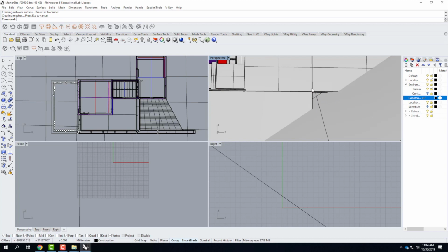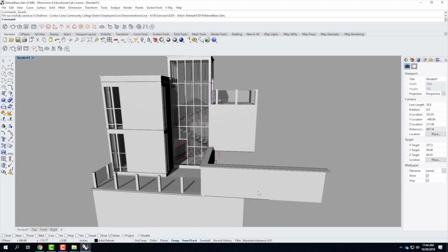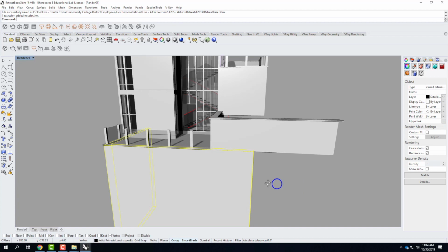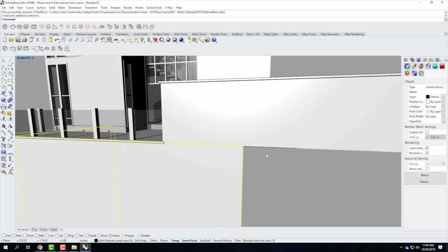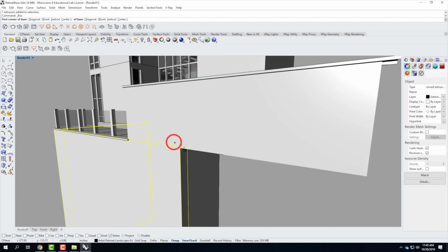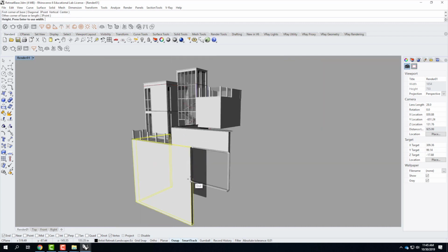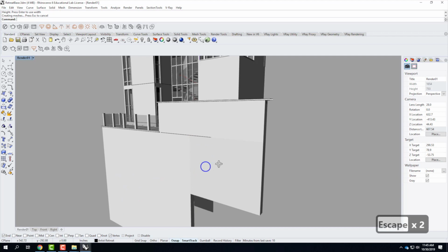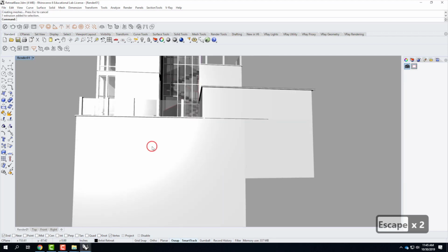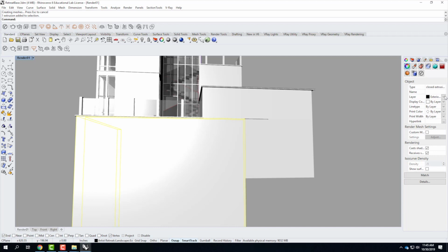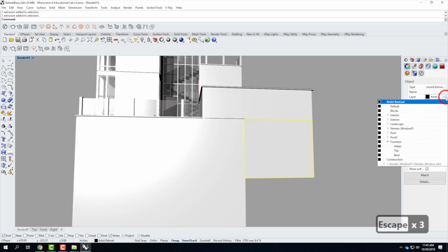I could build it out in this view, but I really need to go back to my original file, which was right here, and make the modification here. So there's that wall that's extending down. Let me create another little box from there to there, and we'll extend this one down. It doesn't need to go as far, but about like that. Then I can go ahead and I should double check that these are on the same layer. They are on the exterior concrete wall layer. So let's make sure it goes on the exterior concrete wall layer.